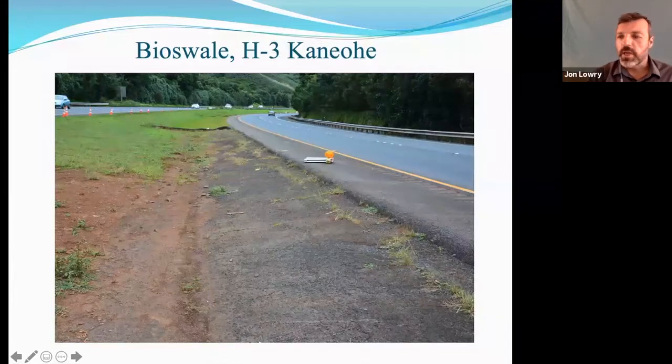Here are some examples of a bioswale on H3 in Kaneohe. This was prior to bioswale construction. You can see the existing channel was a concrete channel. So in this scenario, the water runs quickly off the roadway, runs quickly down the concrete channel and straight into the storm drain without any sort of treatment, and also creates a larger flow event into the system than would naturally occur.